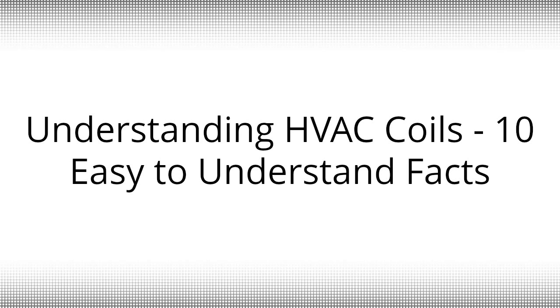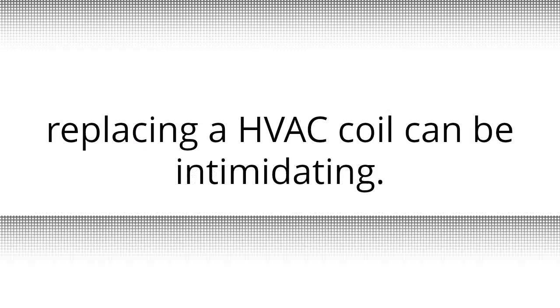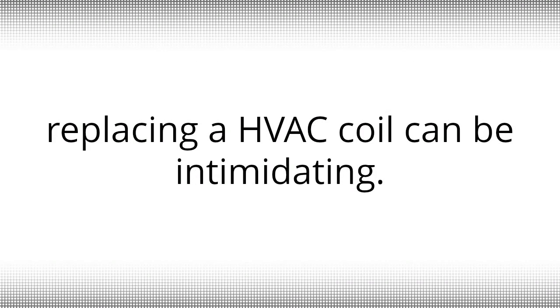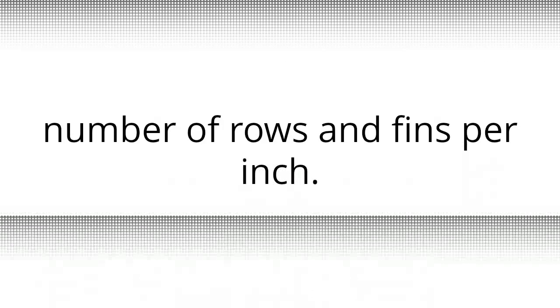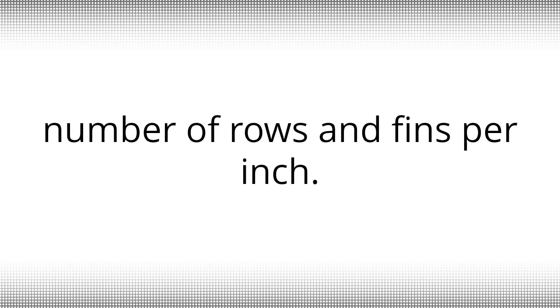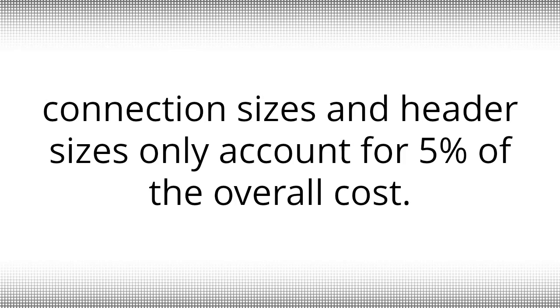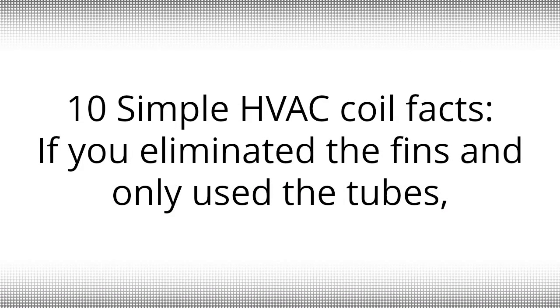Understanding HVAC coils, 10 easy to understand facts with all the types and sizes available. Replacing a HVAC coil can be intimidating. Keep in mind that 95% of the overall HVAC coil cost is the fin surface area, number of rows and fins per inch. Casing dimensions, coil depth, connection sizes and header sizes only account for 5% of the overall cost. 10 simple HVAC coil facts.